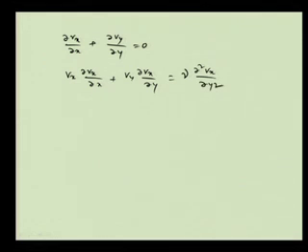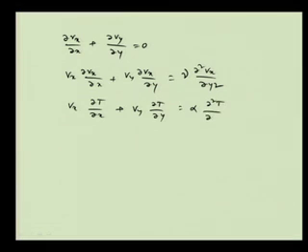That is the momentum equation. And also we had Vx into del T by del x plus Vy into del T by del y, okay, equal to alpha into del square T by del y square. So, these are the three equations we had.